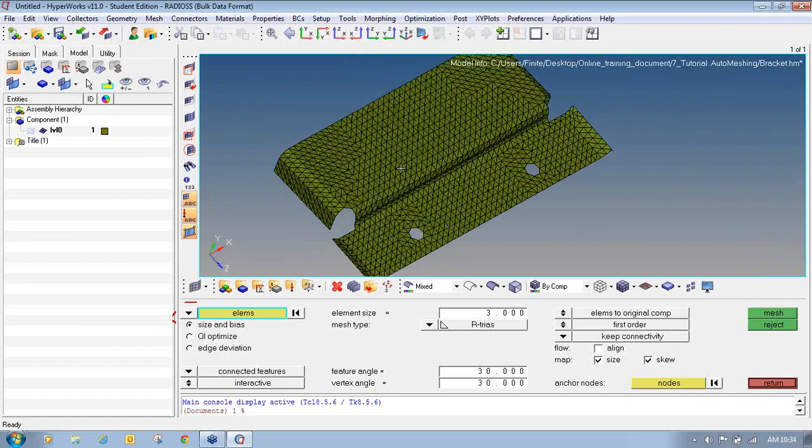So in this video, if I want to summarize, we have seen how to mesh all the surfaces at once, specifying different element size and element types, then practice changing the element density along the surface edges. Also we have seen how to preview the mesh on all the unmeshed surfaces and change the element type and node spacing, that is biasing along the surface edges. Also we have seen how to do remeshing.